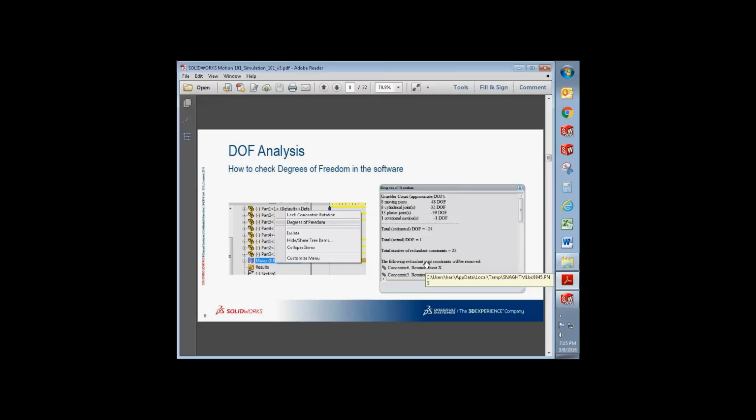So I think this is a little important. I know it is going into the trenches here. It makes the thinking a little more complex, but this is engineering. It's not as easy as what you see is what you get from SolidWorks. If you're doing just velocities and accelerations, you don't need to worry about redundancies. But if you're trying to look at joint forces, this is going to have a big impact, because if it removes redundant degrees of freedom, you're not going to get any force there, and that's not right. So there are ways you can get around that.